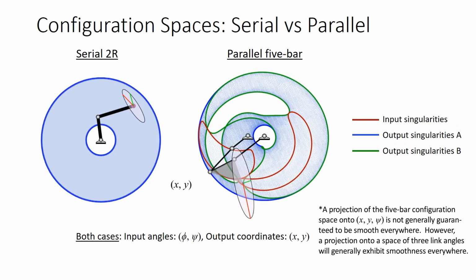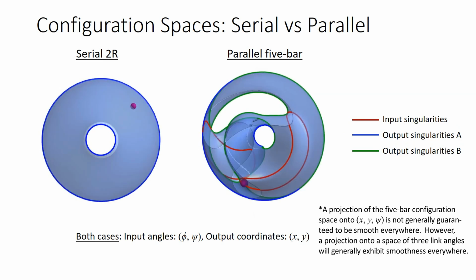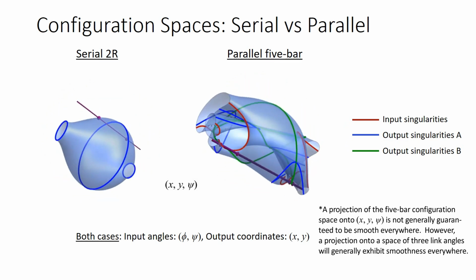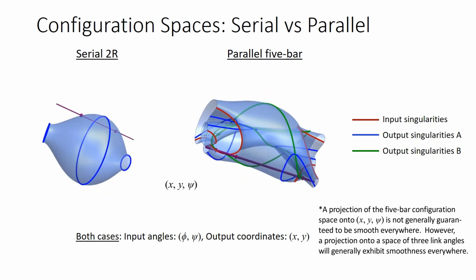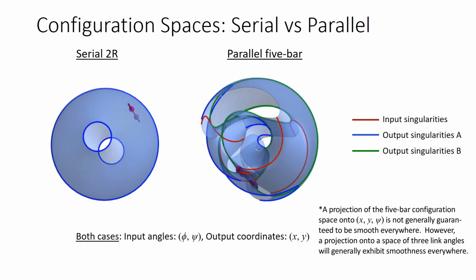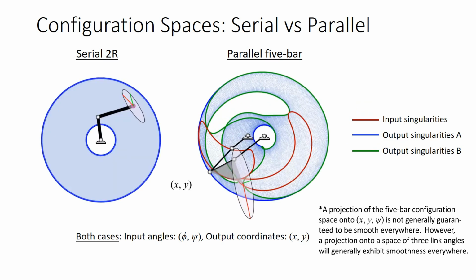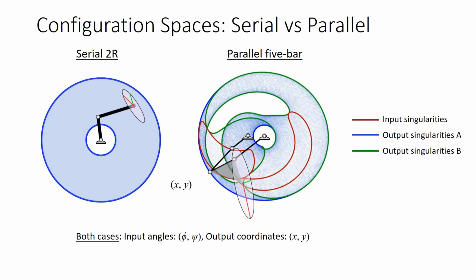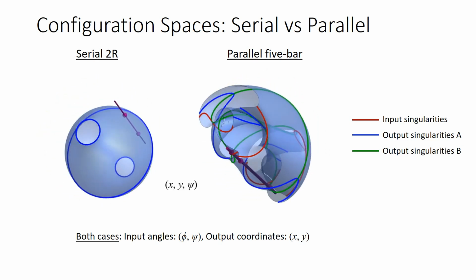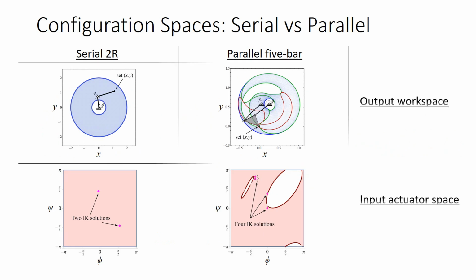When projecting them onto 2D, everywhere the surface turns back, forming smooth fold shapes, this casts edges onto the 2D projection plane. Viewed in 2D, the configuration space is no longer smooth, and the casted edges form curves of singularities. In this 2D projection, the singularities form boundaries where the mechanism could configure on one side, but not the other.